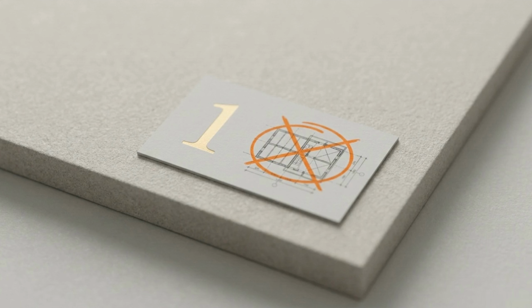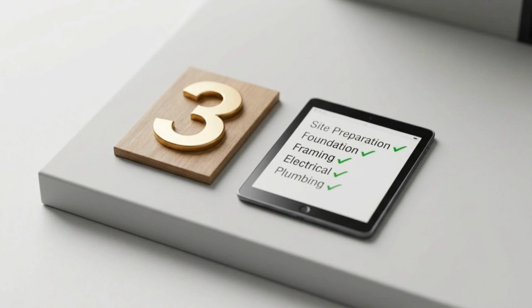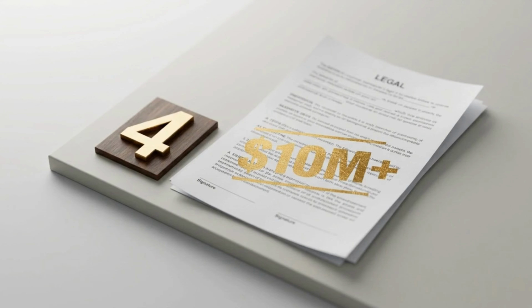To execute this correctly, follow the 5 golden rules. 1. Eliminate risk at the drawing board. 2. Prioritize collective protection over individual PPE. 3. Document every residual risk in the DfS register. 4. Remember that projects over $10 million require an appointed DfSP for legal design approval.